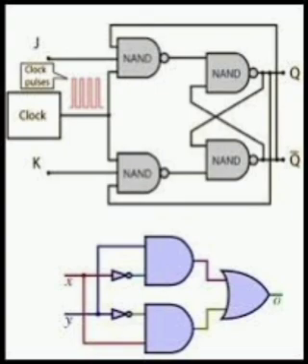Given dmux 1 is to 2 to be implemented mux 1 is to 4, required number of mux equal to 1 plus 2 equal to 3. Given dmux 1 is to 2 to be implemented mux 1 is to 8, required number of mux equal to 1 plus 2 plus 4 equal to 7. Given dmux 1 is to 2 to be implemented mux 1 is to 16, required number of mux 1 plus 2 plus 4 plus 8 equal to 15.